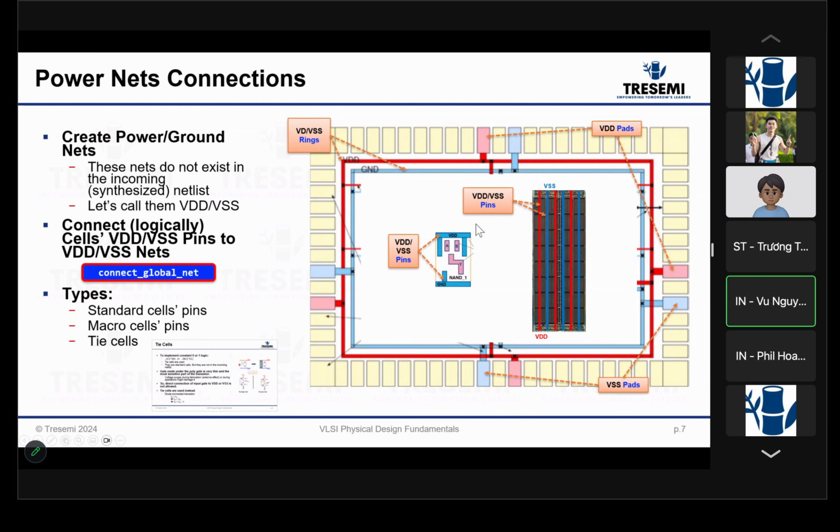No, that is the point that is important. That is the IR graph, that you distribute them, spread them out. So anywhere in the logic, any cell can draw power and get from as close to the source as possible. The source here means the power supply pad or pin. Yeah.